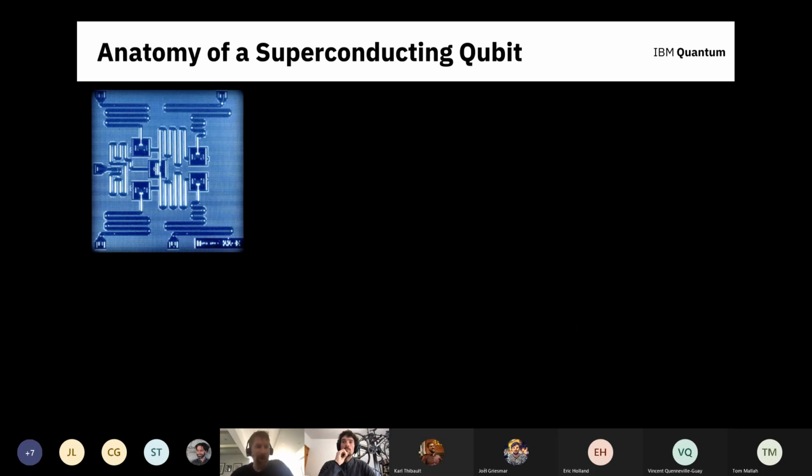So we really like superconducting qubits at IBM because it leverages all the skills and ability that we've developed over the years of CMOS, because it's built in much the same way, but instead of patterning semiconductors, we're patterning superconductors. So essentially we start out with, say, this 5-qubit device. All the parts you can see right now are a thin layer of niobium that sits on top of silicon. Now the silicon just kind of sits there and doesn't really contribute anything.